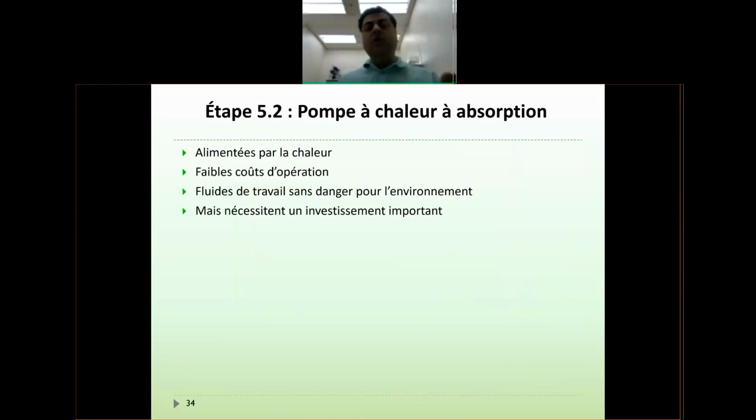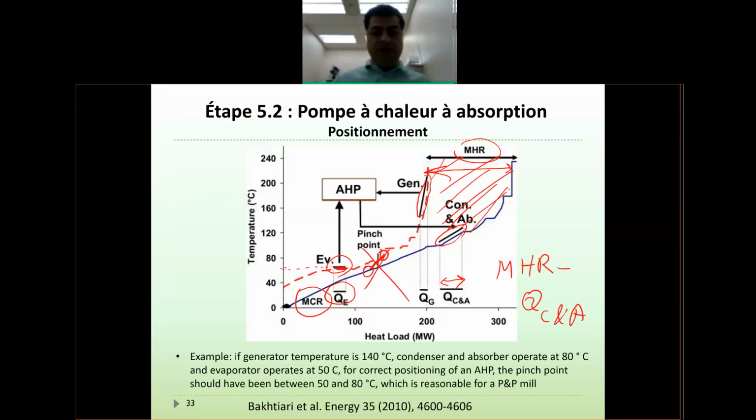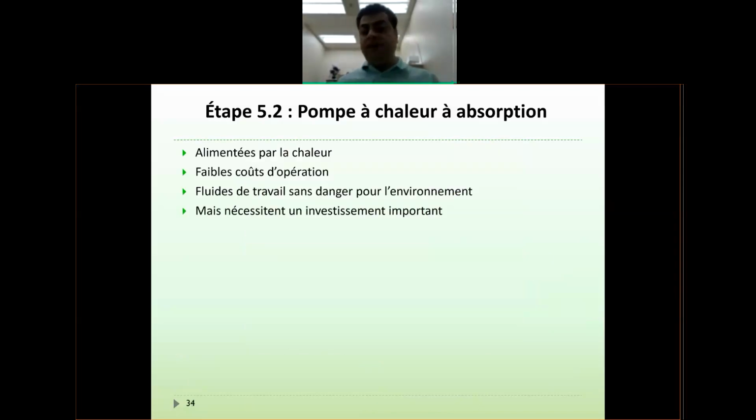By the way, there are some remarks here. A heat pump is very interesting equipment because you take energy from a low temperature, as you saw here, and you lose energy at a higher temperature. For example, here the temperature is 120. It's a very interesting thing, but you have to be careful. In terms of operation cost, it is not very expensive. But in terms of investment, capital cost, heat pumps could be expensive.